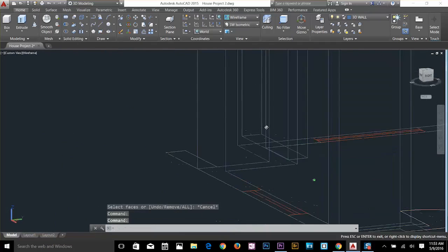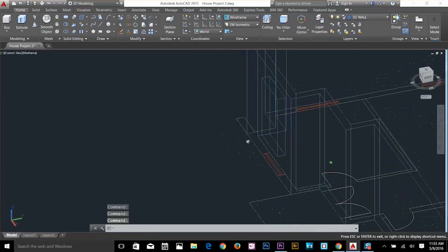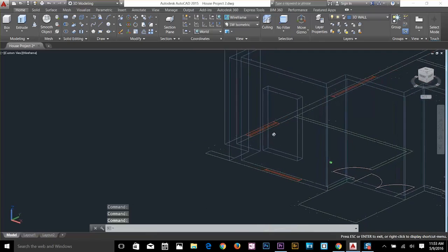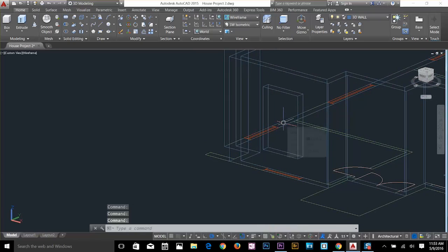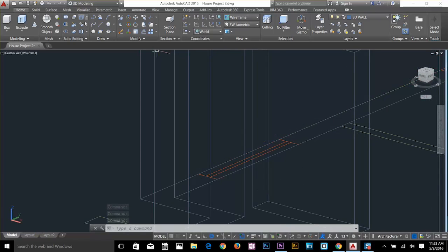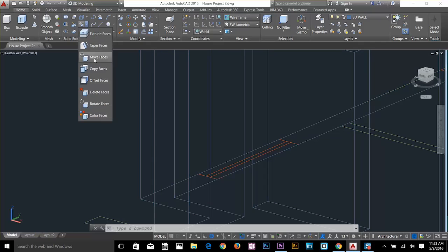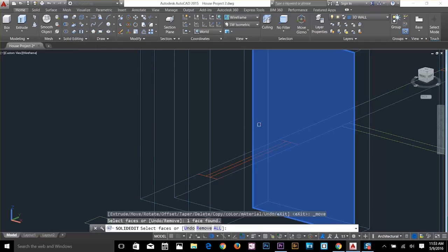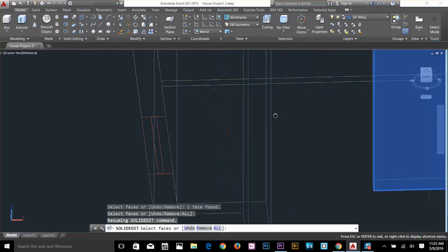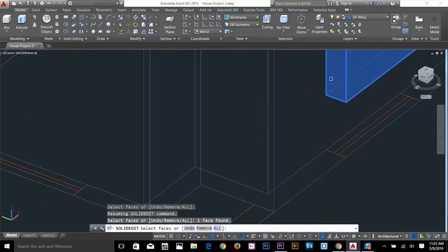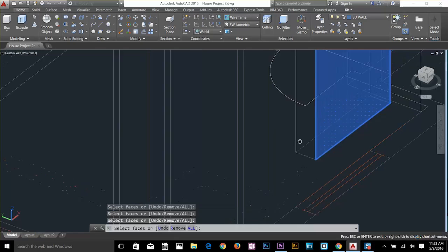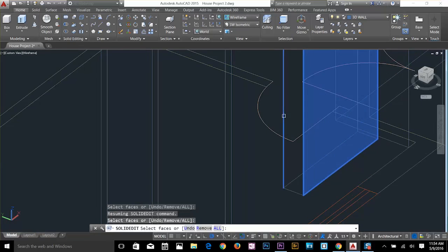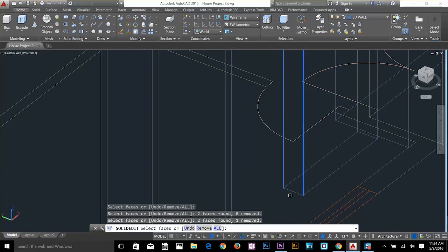So to select that face, I have to come to this viewport. So how am I orbiting throughout my 3D space is hold down shift key and use your mouse wheel and drag. That will orbit that. So I'm just gonna say move face, select this face, or maybe I've got the other face, select that face. Alright, I've got this face now.